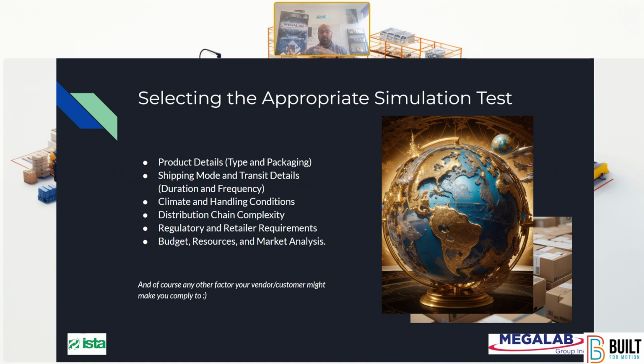Now, the second thing we generally look at is, how is it being transported, right? Is this being moved around on mainly truck cargo? Is it ground? Does it take air freight? If it does take air freight, is there anything semi-permeable as a barrier that's prone to burst, or that's something to be evaluated? Can it be pressurized? So that's a whole element of investigation in determining the appropriate test series. The third element we generally look at is climatic and handling conditions. Depending on the materials your packaging is made of, certain climatic conditions can be more detrimental to the integrity of the package.